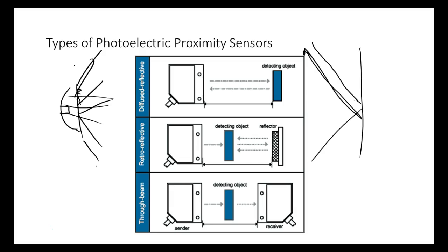But we also use them to reflect light. So these guys, would they be true or false when there's no object there? They'd be true when there's no object. So it gives us the same thing as the through beam, it's just that the distance would be a lot less, right? Everybody okay? What I do now is the transmitter and the receiver are in one unit. Are we okay? So this will be false when the beam breaks between the retroreflector and the transmitter, and it'll be true when there's not a part there.